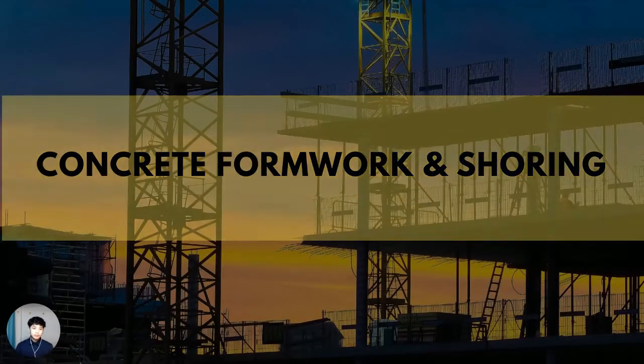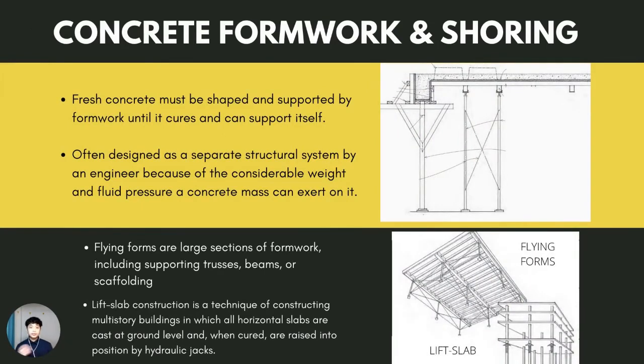Okay, for the concrete formwork and shoring, when new concrete is laid or poured, the fresh concrete must be shaped and supported by formwork until it cures and can support itself. This formwork is often designed as a separate structural system by an engineer because of the considerable weight and fluid pressure a concrete mass can exert on it. The flying forms are a large section of formwork, including supporting trusses, beams, and scaffolding that can be moved by a crane in constructing the concrete roof or floors of multi-story buildings.